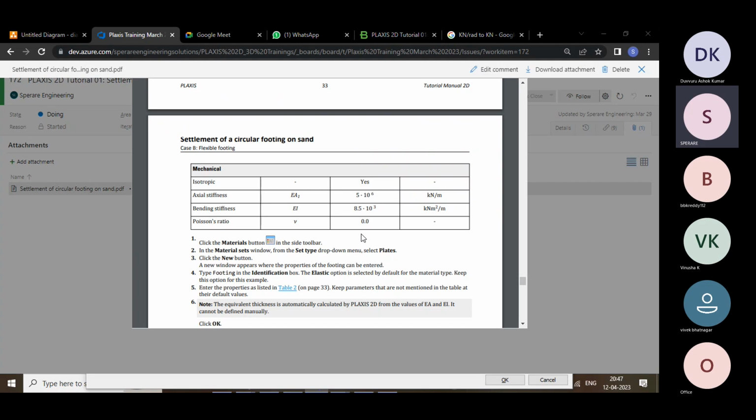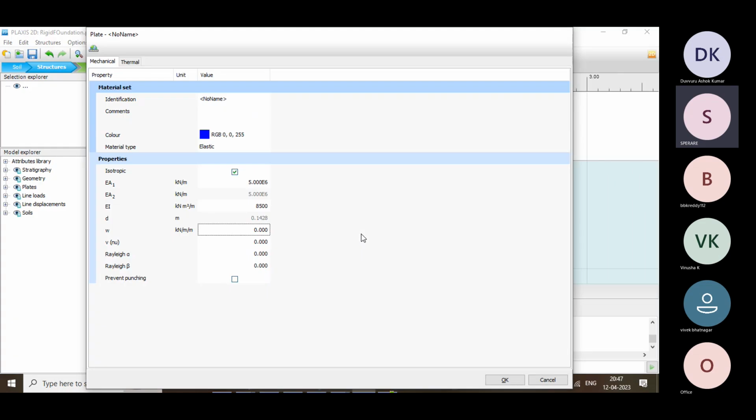And the Poisson's ratio also, they are going at 0, but in reality it should not go like 0. Either it should be like a 0.29 or something. In cases like a 0.22 also, it would be a right solution or not. So provide the materials rightly. Even in the document they have not given the right values, but you just try to provide it. Okay, and the damping values, if I have it, I will do that.